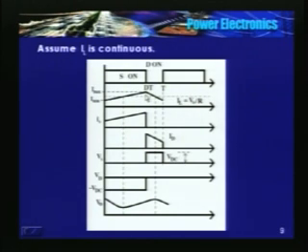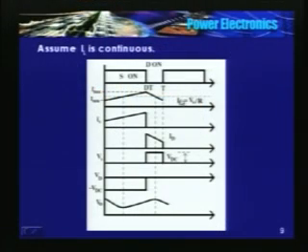No, KCL has to hold good. Beyond this point the inductor current is higher than the load current, so the capacitor charges during this interval, and after this the inductor current is less than the load current, so the capacitor supplies current, because we assume the load current to be constant, and the capacitor discharges.